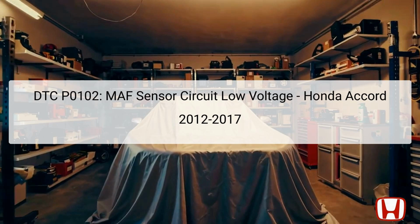When the MAF sensor malfunctions, it can cause significant drivability issues and trigger the P0102 diagnostic trouble code. This code indicates that the MAF sensor is sending a low voltage signal, potentially leading to incorrect calculations by the powertrain control module, PCM. Our troubleshooting will involve steps to diagnose and resolve issues related to the MAF sensor and its associated wiring. We will address possible causes, symptoms, and necessary repairs related to this DTC.